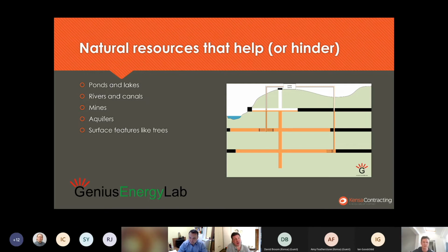So the main energy transfer in a body of surface water is the surface. So solar gains will warm that lake or pond up and evaporative losses will cool it down. On depth, rule of thumb, you need 2 to 3 meters minimum depth. But if you do have something shallower than that, don't rule it out. It just needs a little bit of a different approach as far as design and what we put in the lake is concerned. Okay, does that help? Yeah, well done, Chris.